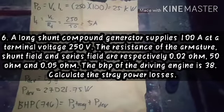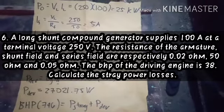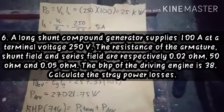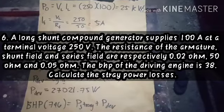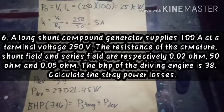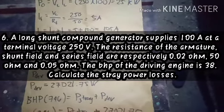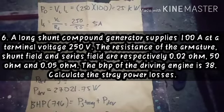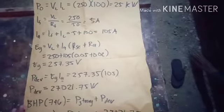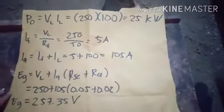Part 2, number 6. A long shunt compound generator supplies 100 ampere at a terminal voltage of 250 volts. The resistances of the armature, shunt field, and series field are respectively 0.02 ohm, 50 ohm, and 0.05 ohm. The BHP of the driving engine is 38. Calculate the stray power loss. So, we find the power loss in the stray.